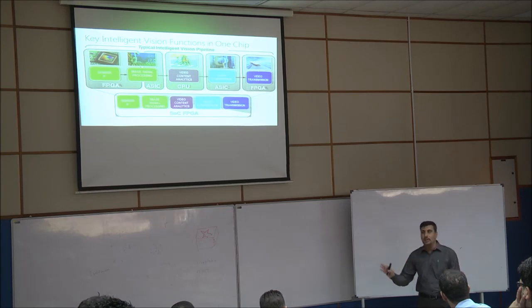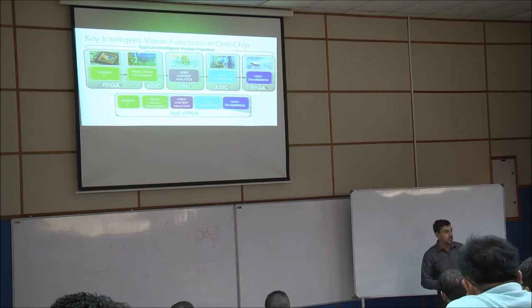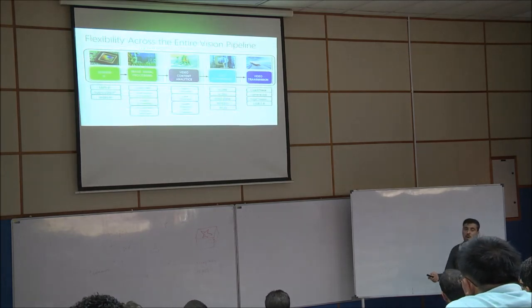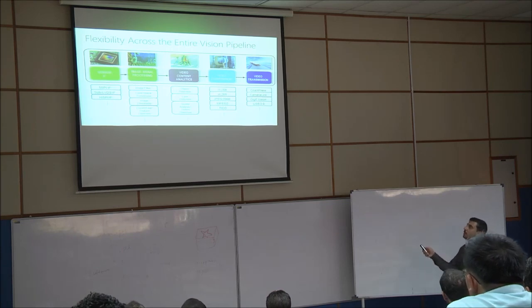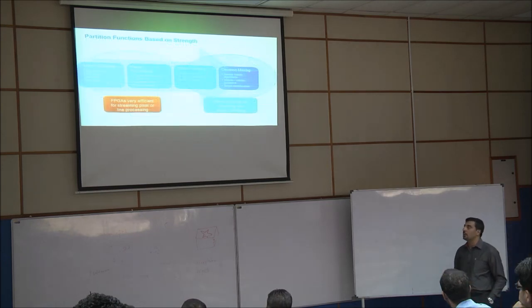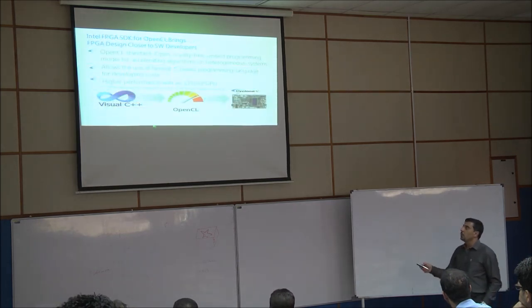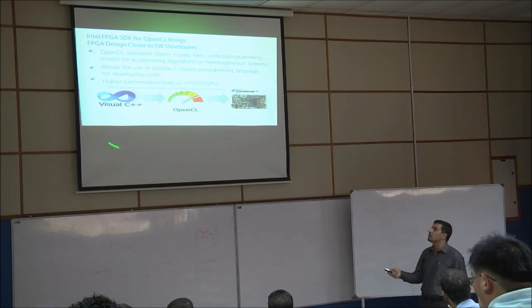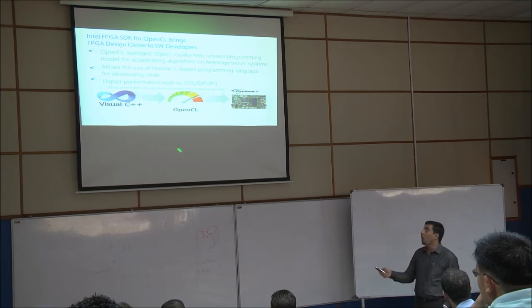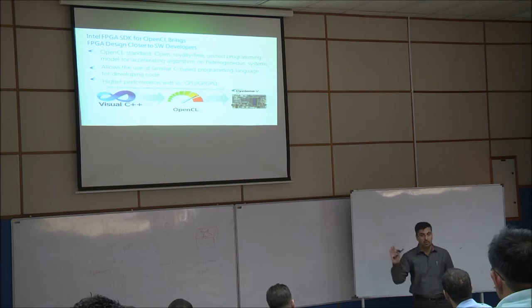Clear? True parallelism, the only technology that can satisfy a high level of true parallelism is FPGA, and reconfigurable technology as well. Clear? So I'm trying to explore this terminology with you. You see how we divided the problem into different sectors inside the FPGA itself. Okay? So partitioning our design, yes, sure, we can do partitioning according to the logic elements and cores we have already inside the chip itself. Then, as I said to you, in addition to using HDL, we can use other languages like C++ or OpenCL. These two languages can be used by us, the users, to utilize the FPGA itself, not necessarily using HDL, Verilog, or VHDL.